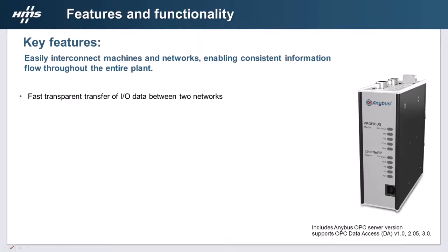But actually what was happening is that the data was being sent byte and word swapped by this Ethernet IP device. So the X-gateway just sent it out to the Modbus side, byte swapped and word swapped. So they were expecting the X-gateway to have done some sort of manipulation on it, but it won't. It sends it out as it gets it.